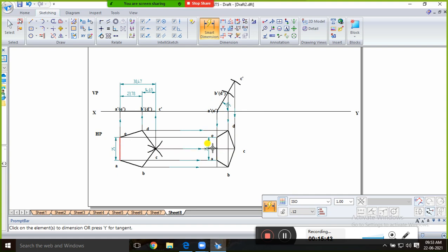So here also the same 25 and here also the same 25. So we have to go with the normal method. We won't find any alpha or beta. Clear? Directly draw the 45-degree line and rest this edge. Is it clear? When we go with the locus method, it means there is a change in the dimension, only then can we go with the locus method. But here there is no change in the dimension, so we are going with the same normal method.